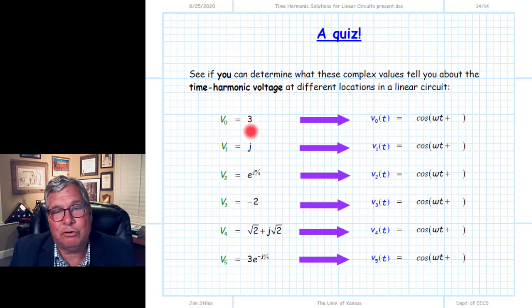And that's the thing you should do in your mind. Anytime you see a complex voltage or current, rewrite it in that Euler form. 2 times e to the j pi over 2. 4 times e to the j pi. That tells you exactly what the magnitude is and what the phase is. And again, this is not notation. This is not phasor notation. 3 times e to the j0 is exactly equal to 3. It's not a notation. It is a mathematical equality to 3.